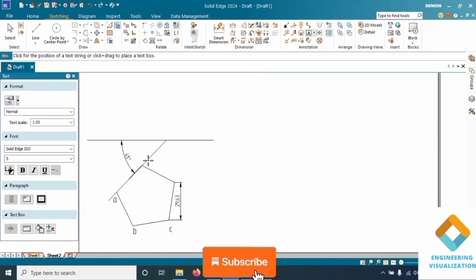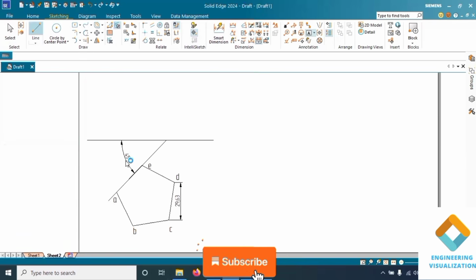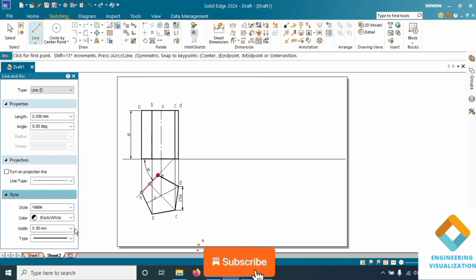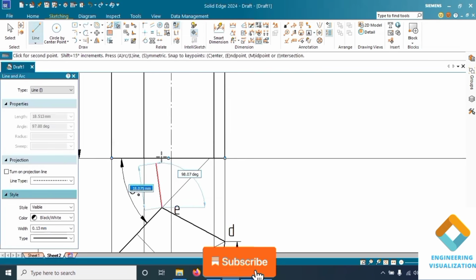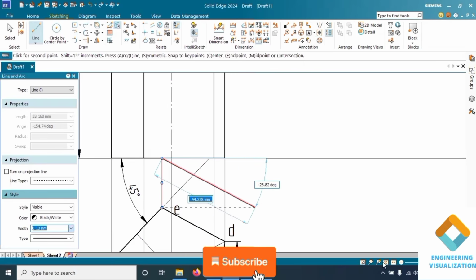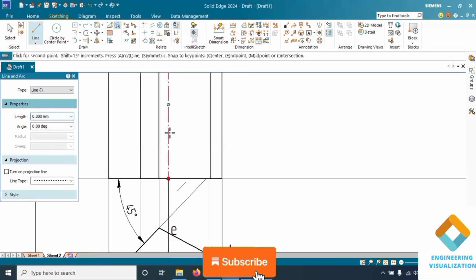After giving the namings, we need to draw at least two or three perpendicular bisectors to get the center point. After drawing the front view, we need to draw the projection line for this end also. So draw a length of 30 from the base.